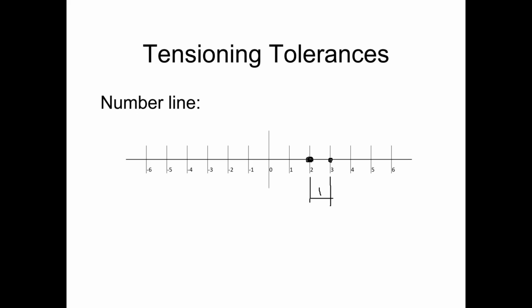So it's that third question that can sometimes mess us up, and using this number line is a great way to visualize that tolerance, answering that third question with regard to tolerance. That's what I would recommend that you do on your scratch paper if you're doing a test, or if you're doing one of these in the plant, on the side of your tensioning report.